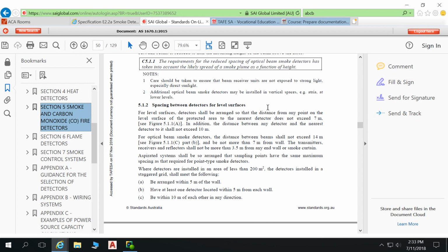That hydrant, it's not a large piece of equipment. That's like the hydrants that you see around here, the 150mm pipes with the Storz fittings on them. Typically the big boxes you see around the place that say fire hydrant, they've got a fire hydrant booster within them, which is a pump system which provides pressure. So it sucks it out of a tank and provides all that pressure. We're not providing large boxes on each of our floors. We're providing accommodation for that pipe and the Storz fitting on it, and then the hose reel next to it.